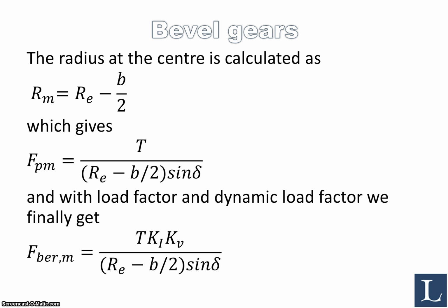And with a load factor and a dynamic load factor that we can get from diagrams, we finally get a force that we can use to calculate contact stresses, the expression shown at the very bottom here.